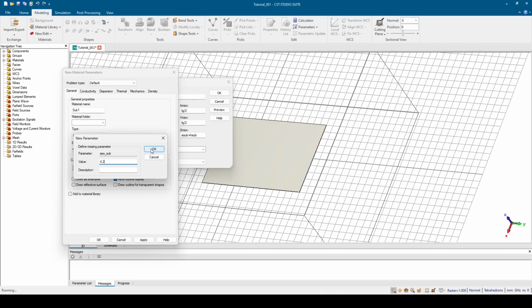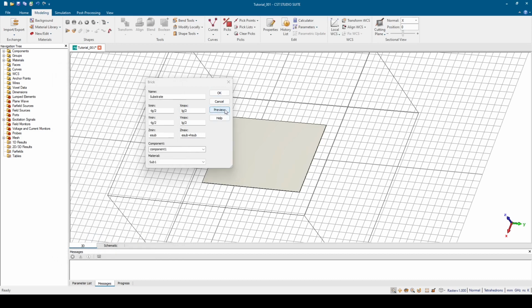manage the FR4. We can actually pick up the material, but usually I prefer starting without loss, and then we can add the loss later. That's all. Okay, and then the elevation of the substrate we'll do from the ground, right after, like right above the ground. So start from here. Let's say I'll start with 0.5 millimeter or something.